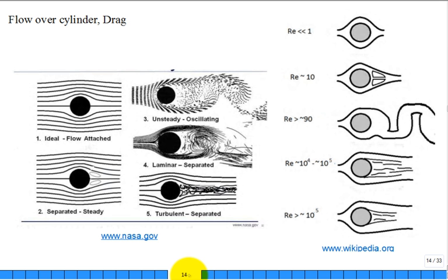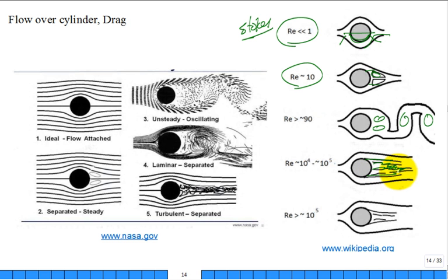We talked about the flow over a cylinder, did we not? We talked about when it's low Reynolds number, laminar flow, there's no separation. The flow reattaches in the back. It's actually quite complicated, the pressure distribution around the cylinder from 0 degrees out to 180 degrees. But there you go, Stokes flow, another name for that. As the Reynolds number gets larger, you get the recirculation because of separation. Then you'll have shedding of vortices on the backside. Then you'll get a wake region, with much smaller vortices being continuously shed. And that separation point moves up.